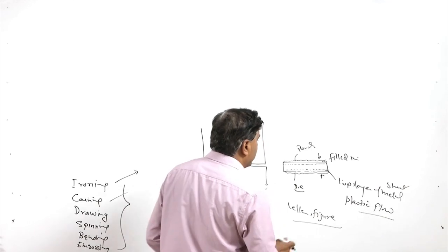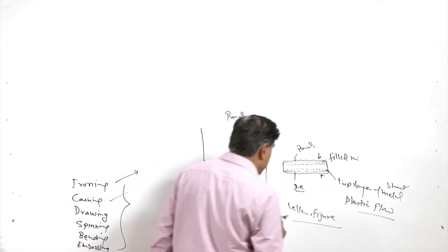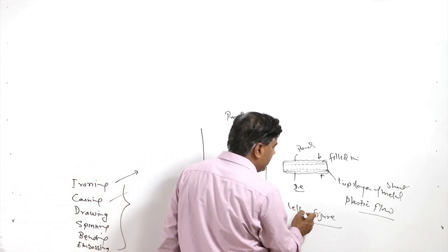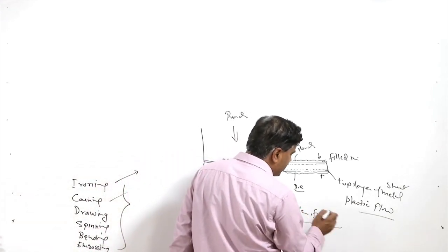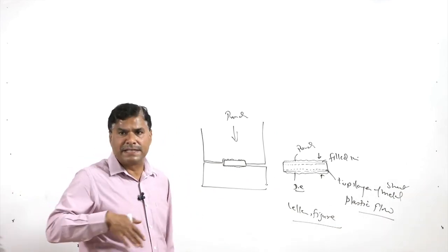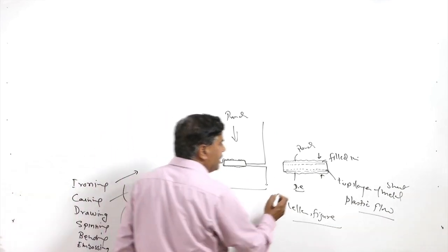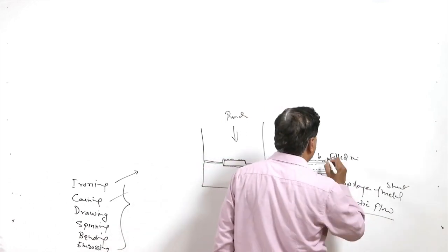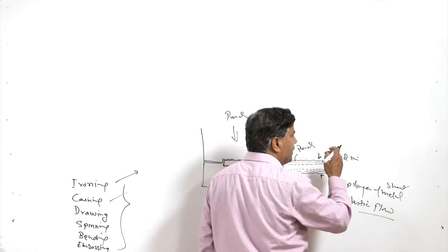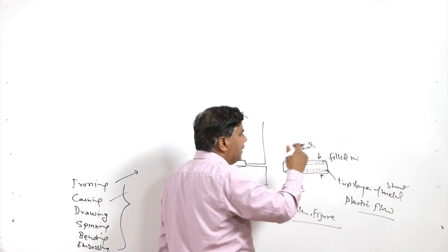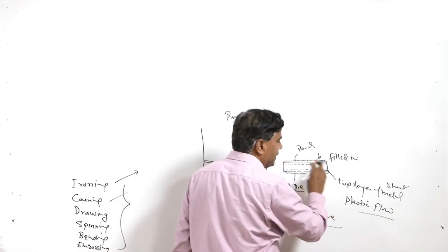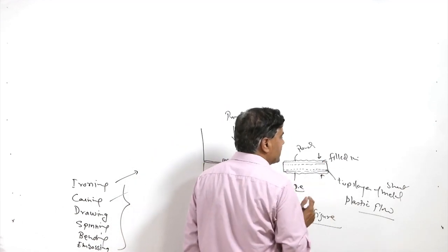To ensure that the flow of the metal into these fine details is complete and all the fine details are produced, very high pressure is used so that the metal at the top layers flows into the cavities both in the punch as well as in the die side and develops the desired impressions in the coin.